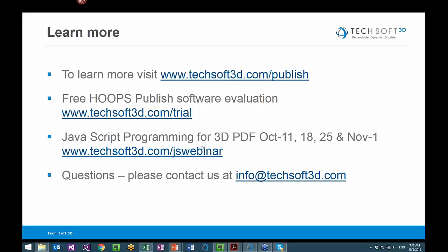In that case, that bridge would only take the surface data, the triangulated, tessellated data that exists in the Hoops scene graph, and then it would embed that in the PDF because we don't have that BREP geometry. On top of that, though, if you have that BREP geometry within your authoring CAD system, that absolutely can be pushed into the PDF using Hoops Publish if you so desire.